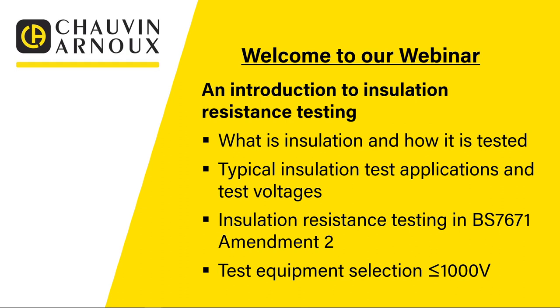We're going to start off with what insulation resistance is and how it is tested. We're going to look at some typical applications and test voltages. We'll look at the insulation resistance testing requirements of BS7671 Amendment 2, the new standard that came out earlier this year in the UK. And we're going to look at selecting insulation resistance test equipment. For this session, as I said, we're going to concentrate on voltages of 1000 volts and below. The 5 kV, 10 kV, 15 kV testers we'll focus on in the next session. In this one, we're really looking at the low voltage type applications.